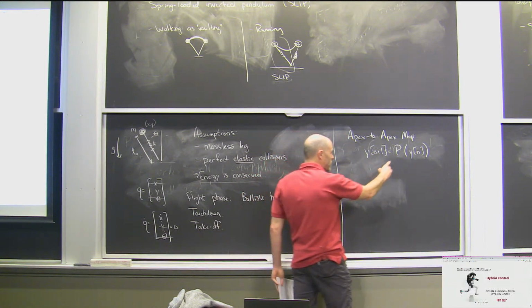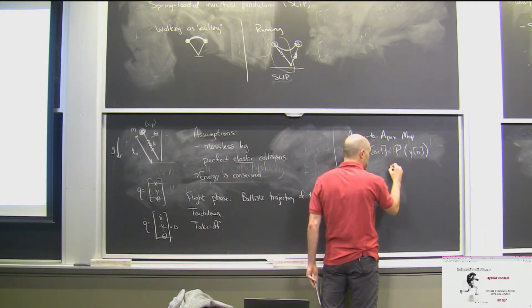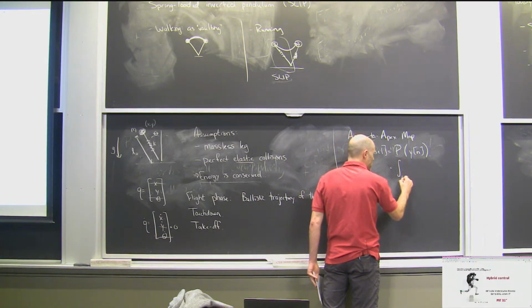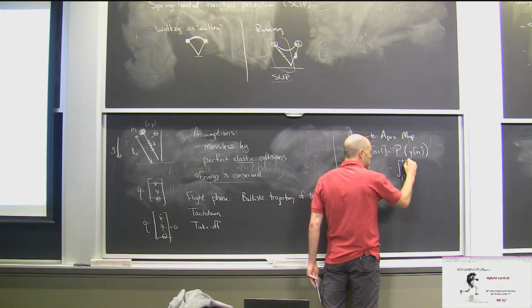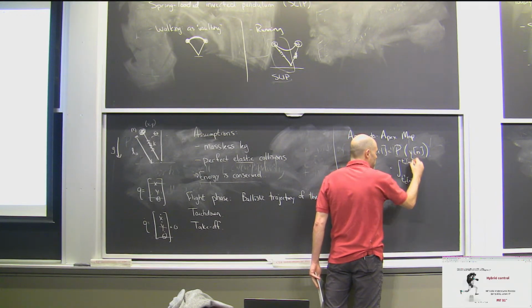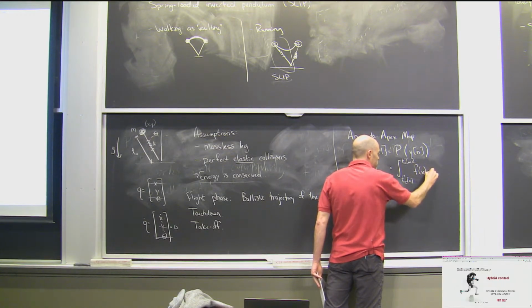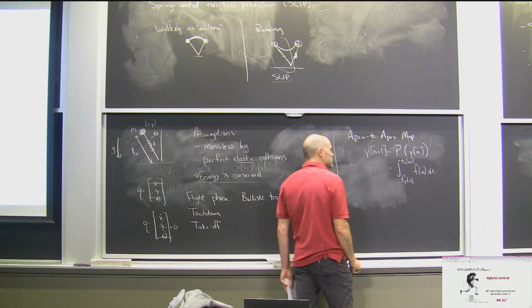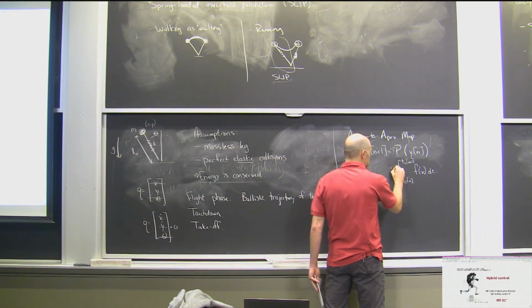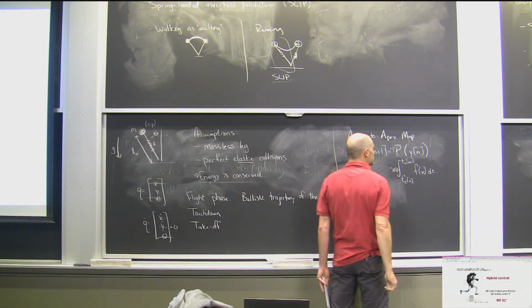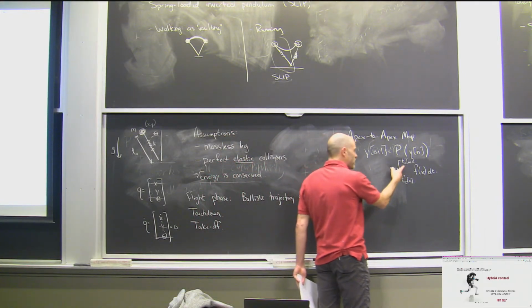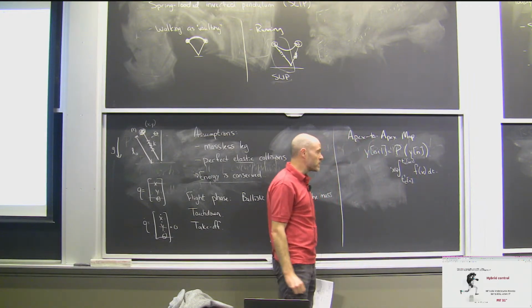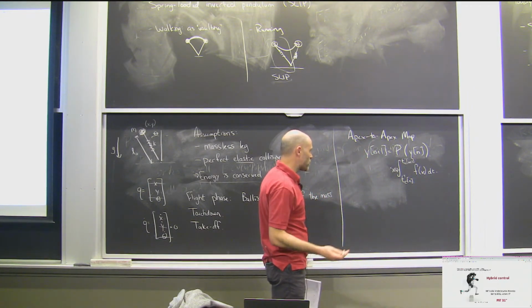You should think about what this P is hiding: it's actually an integral from the time of the nth collision to the n plus 1 collision of the continuous dynamics, right? And in the rimless wheel, I was actually able to integrate that in closed form and get a closed form expression for P. But more generally, we're rarely going to be able to do that.